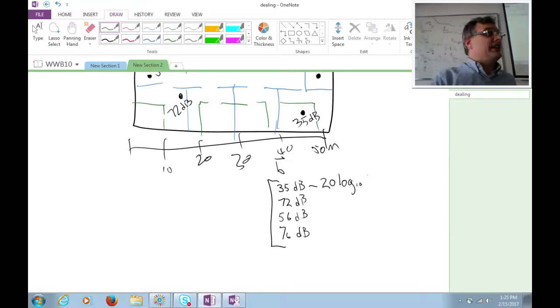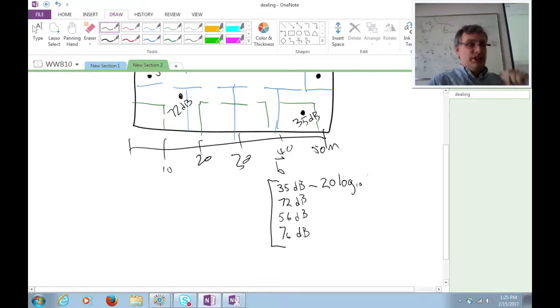And that's not to say that this wall, if I took it into an anechoic chamber and put a transmitter on one side and a receiver on the other side, that I would get 4 dB or whatever the Seidel-Rappaport coefficient would be for that. That's not what it's saying. It's a trend spotting tool. It says on average, that's the kind of loss that you would expect when 1 or 2 or 3 of these things is in between you.